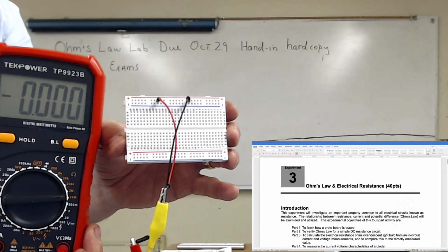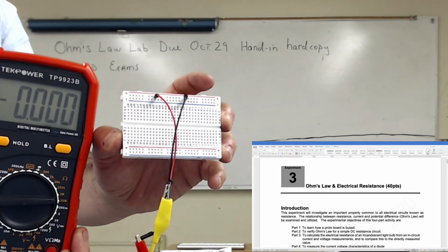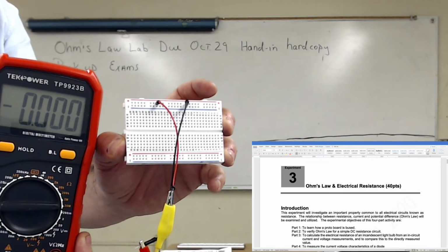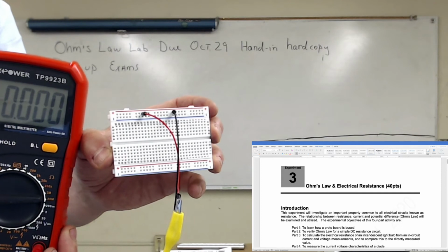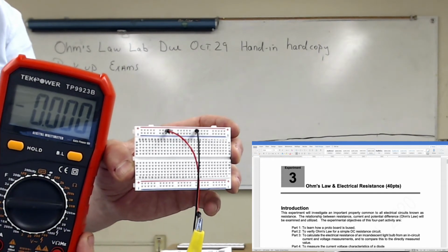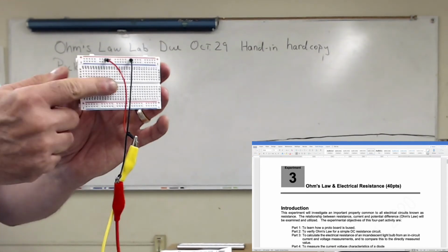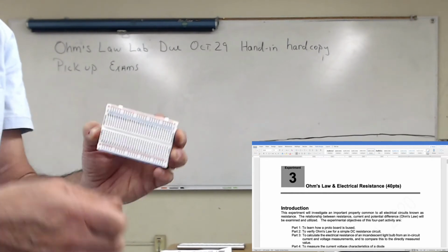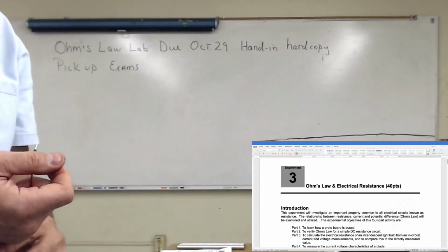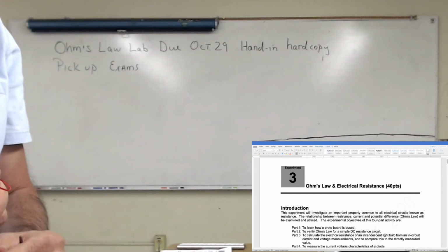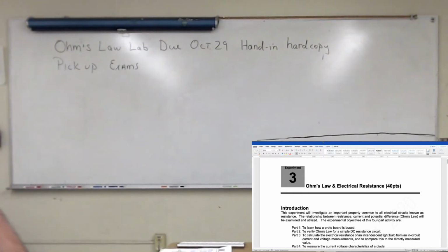What other pairs are connected? And so what you would do then is take one of these and move it to another set of holes and see if they're still connected. Are all the ones along that line near the red plus connected to each other? That's one thing you want to check. Okay? And so what you're going to do is you want to see how all these holes are connected. Now granted, there's a pattern, so you do not have to go through every single pair of holes to check if they're wired. You'll see a pattern, and the pattern will be pretty straightforward. Then what you're going to do, let me scroll down.